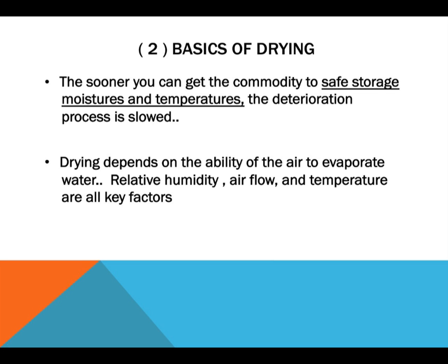Two basics of drying, at least that I would boil it down to. The sooner you get the commodity to safe storage, moisture and temperature, the deterioration process is slow. You've heard that consistently all the way through today, from this morning until our earlier speakers. You need to get that moisture level down and get the temperature to acceptable levels in order to store it for any period of time.